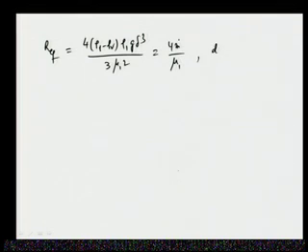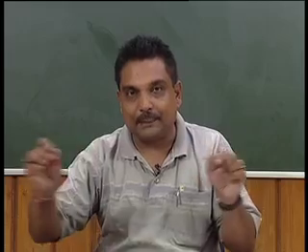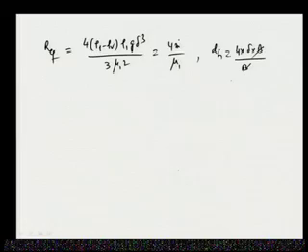Because here dH, hydraulic diameter, is basically 4 into delta into B by B. B is the wetted perimeter, the breadth. So, this B we cancel, and it becomes 4 into delta. So, if you put the values of dH and Vx bar, which is known, then we can find out this expression.